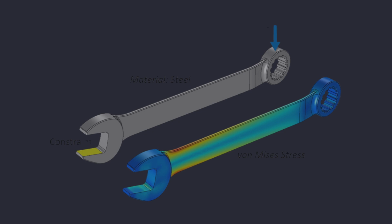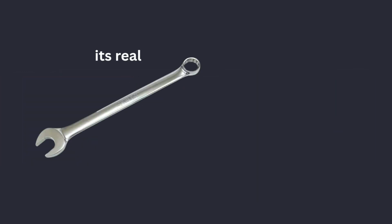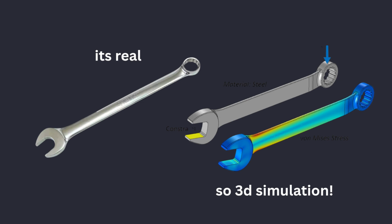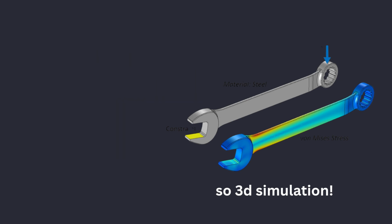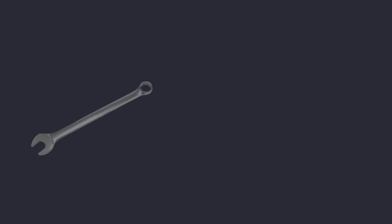Problem number 2 is jumping straight into 3D. The second mistake is something I see all the time. They're real objects, so I need to simulate the entire 3D object. Not necessarily. Before opening the software, ask, what question am I actually trying to answer? Let's say you have a wrench, and you want to know what's happening around a particular region where the stress is concentrated. Do you really need to model the entire wrench in full 3D?